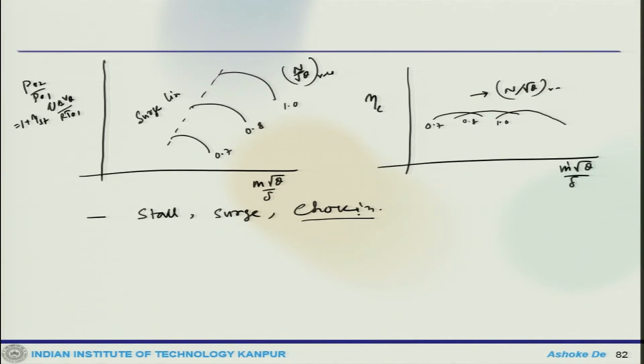As we have talked earlier, the possibility of flow separation is higher at later stages. Now, flow separation may reduce the effective flow passage such that the latter passage works as a throttling valve, and also in the surge it is a violent unstable condition, or rather operation of the compressor at low mass flow rate.